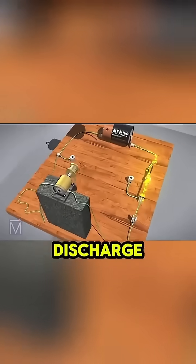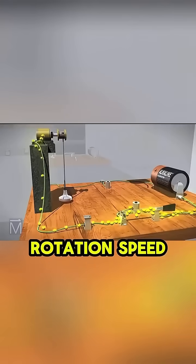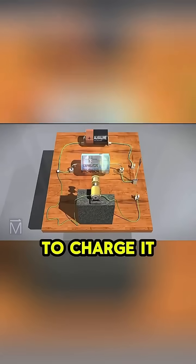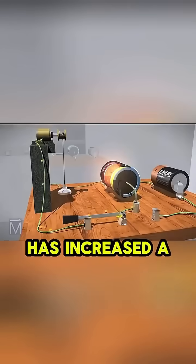Furthermore, a capacitor's discharge speed is much faster than a battery's. In this setup, a battery directly powers a motor, and its rotation speed is slow. Now, if we add a capacitor, first we use the battery to charge it, then we switch the circuit to let the capacitor power the motor directly. You can clearly see the motor speed has increased a lot.